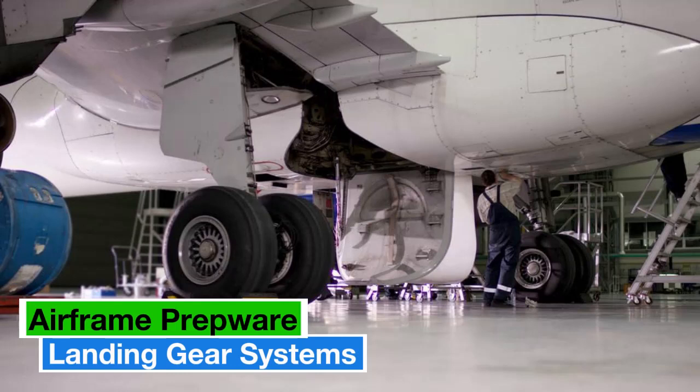A horn or other oral device and a red warning light. The left brake is dragging excessively on an airplane on which no recent brake service work has been performed. The most probable cause is foreign particles stuck in the master cylinder compensating port.